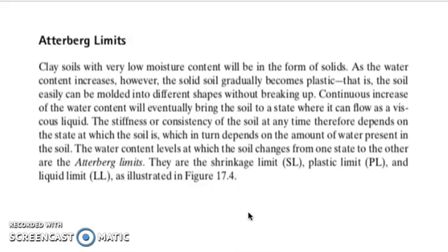As we continue to increase the amount of water, the clay soil will flow as a viscous liquid. So the stiffness or consistency of the soil at any time depends on the state the soil is in, which in turn depends on the amount of water present in the soil.